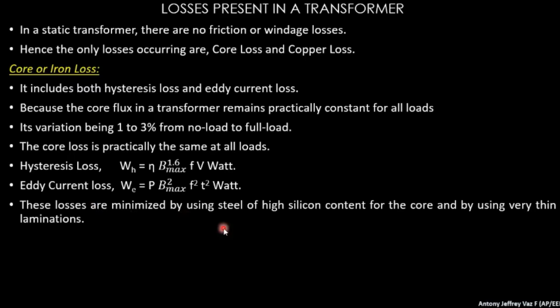These losses are minimized by using steel of high silicon content for the core and by using very thin laminations.